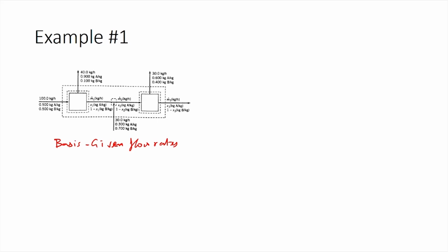We will first start with the overall system. Why do we want to start with the overall system? If you look at the different systems, the overall system gives you one piece of information: the unknown is only one stream, which is M3. You do not know the mass and the composition of the product 3 stream. All the other streams which are crossing the system boundary are known. So, we could start with the overall system. Let us start with this and perform these calculations.